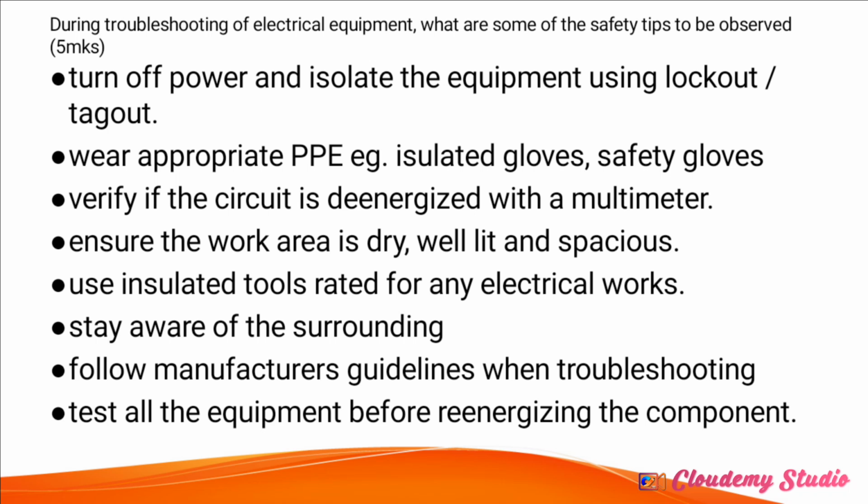After drawing it, go perform the installation, and leave a copy of that wiring diagram with the engineer or the owner of the house. In case you are not around and there is a fault, if another technician comes to troubleshoot, he can request the wiring diagram, go through it, and understand the type of installation that you did at that particular place.